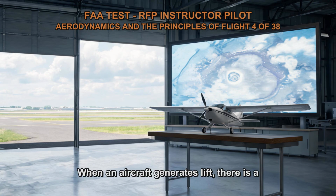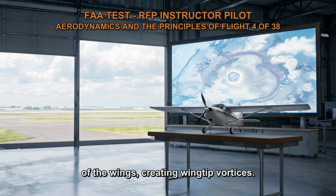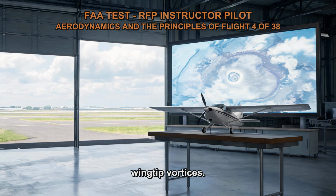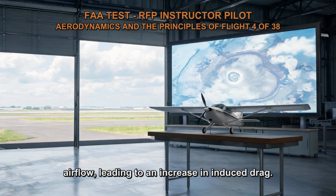When an aircraft generates lift, there is a pressure difference between the upper and lower surfaces of the wings, creating wingtip vortices. At lower airspeeds, the airflow over the wings becomes less streamlined, resulting in stronger and larger wingtip vortices. These vortices cause a downward deflection of the airflow, leading to an increase in induced drag.